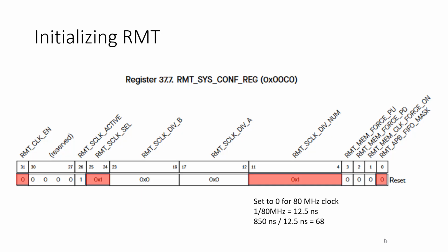we have this clock divisor, right? So you start out with the 80 megahertz, and you can divide it down. In this case, we're not going to use the divisor. We're just going to not divide the 80 megahertz clock. We don't want to divide it, right? So you'll notice that there's a 1 in here by default. And you would think that a 1 would mean that you divide by 1, which means that you don't divide, right? Dividing by 1 doesn't do anything, right?